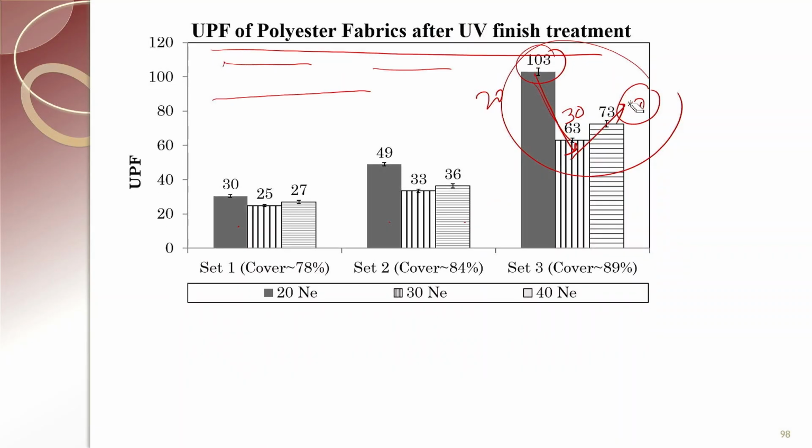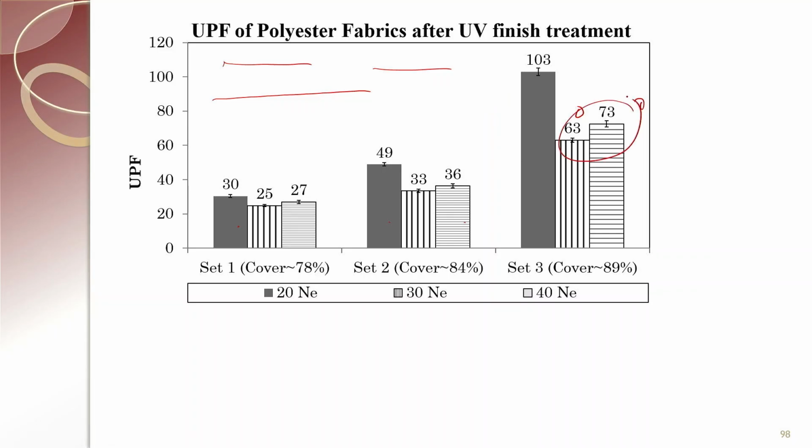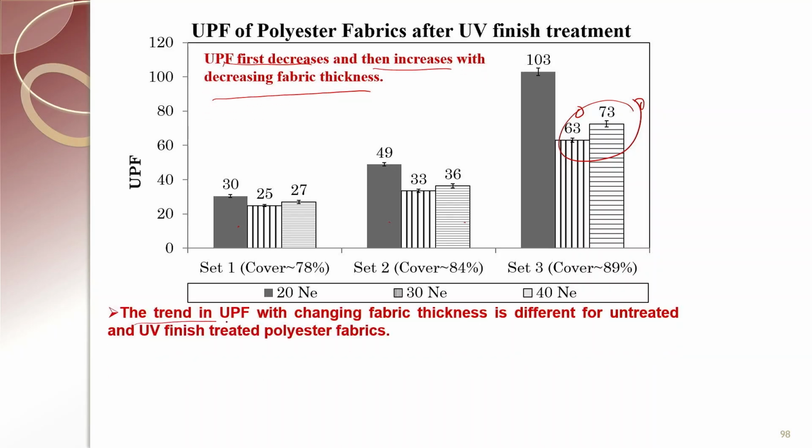But the interesting thing is that this increase is the interesting thing. UPF value is increased after the initial decrease. The trend in UPF with the changing fabric thickness is different for untreated and UV treated fabric.